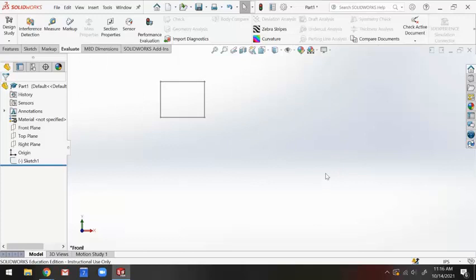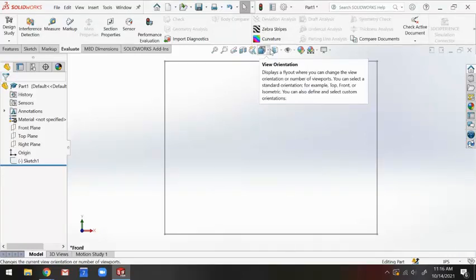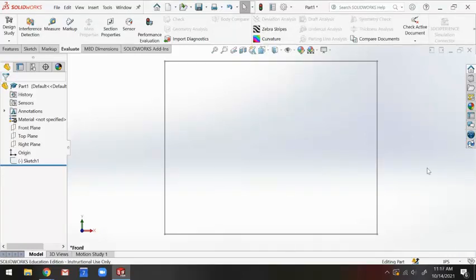I just drew something, so it doesn't really matter what it looks like. But notice I zoomed in and out, and I get some weird things, like, uh-oh, I lost it. Sometimes that happens. Something that can help is to hit Control-1 on the keyboard, and that zooms to the current view, taking the current things that we have and making them show on the page.